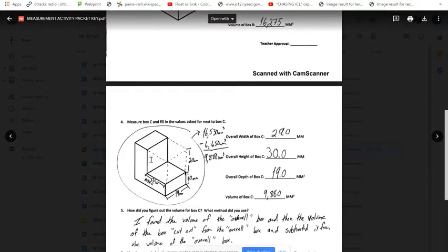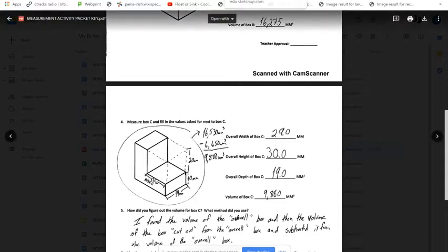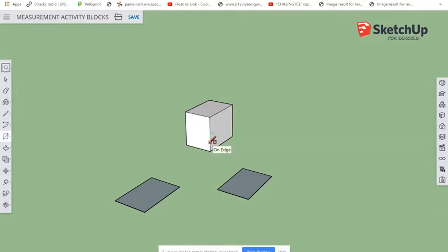Now, if we look at our key, this shape is at two different heights. It's got a section that's right here at a height of 30 and a section that's right here at a height of 10. From this edge to this edge, it's just 10 millimeters. So what I'm first going to do is draw a line that goes across the two-dimensional rectangle that I just made.